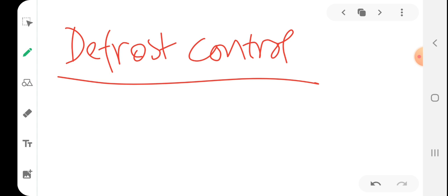Okay, so where freezing is the goal, however, heat from some source must be periodically applied to the evaporator coil to melt the accumulated frost. These defrost cycles are often initiated by timers. This is appropriate, but using a timer to establish the duration of the defrost period tends to waste energy. Evaporator temperature is a better indicator of when to stop defrosting.